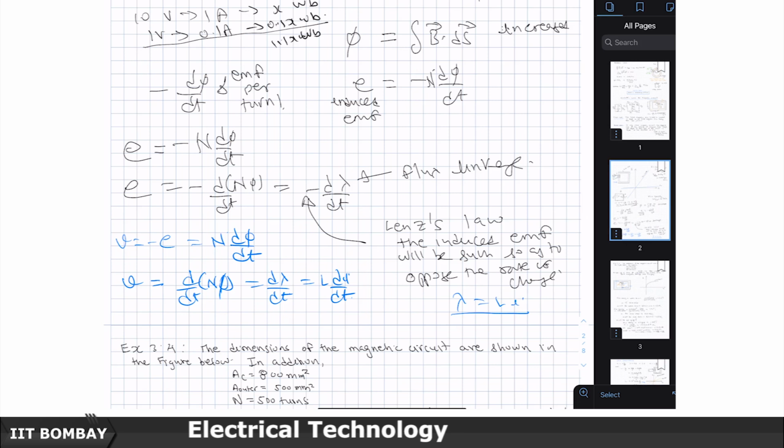So, you should understand that what you learnt earlier in schools, which is E equal to minus n d phi by dt, is absolutely right, but it was based upon a convention that all voltages, whether applied or induced, are written in an additive sense when you circle around the loop. It is also called a generator convention, and it is cumbersome to carry this minus sign everywhere.